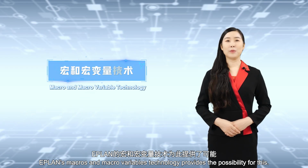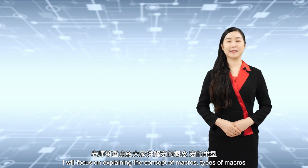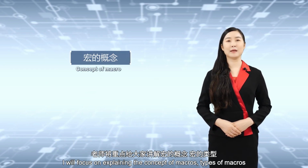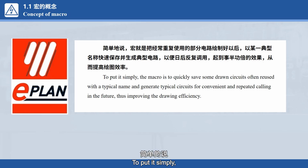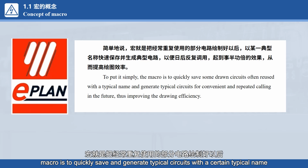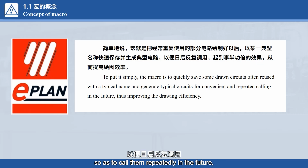E-Plan's macros and macro variables technology provides the possibility for this. In this chapter, I will focus on explaining the concept of macros, types of macros, and how to create macros. To put it simply, a macro is to quickly save and generate typical circuits with a certain typical name after drawing some circuits that are often reused, so as to call them repeatedly in the future, thus achieving twice the result with half the effort and improving the drawing efficiency.